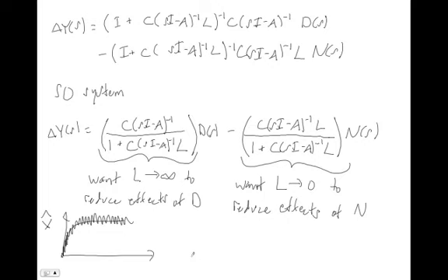You can make your L gain smaller to reduce the effects of that, so your output doesn't sit and jitter, but then it doesn't reject disturbances as well, and it doesn't reject modeling errors as well. So there's no simple solution. There's no perfect solution. Our goal is to find a reasonable trade-off to balance these two effects. And that's exactly what the Kalman filter does.